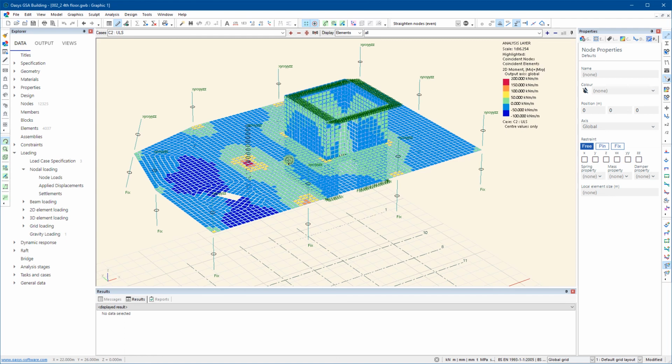I think I would just end here by saying, well, as you've seen, although most of this went relatively smoothly, there were a few issues, and even though I've been using GSA for a long time, still these things do come up. So don't feel bad if it takes you a bit of time to get used to the software. And again, often stepping back and just thinking about what's going on and doing the basic checks on whether you've put in the right restraints, whether you've defined the material properties correctly, and also, as you just saw, whether the loading is correct, especially if you've extracted the analysis. Has anything odd been carried over? Again, it's all the kind of checks that you need to do both in your design project, but also in practice. It's what we would do in the design office as well.